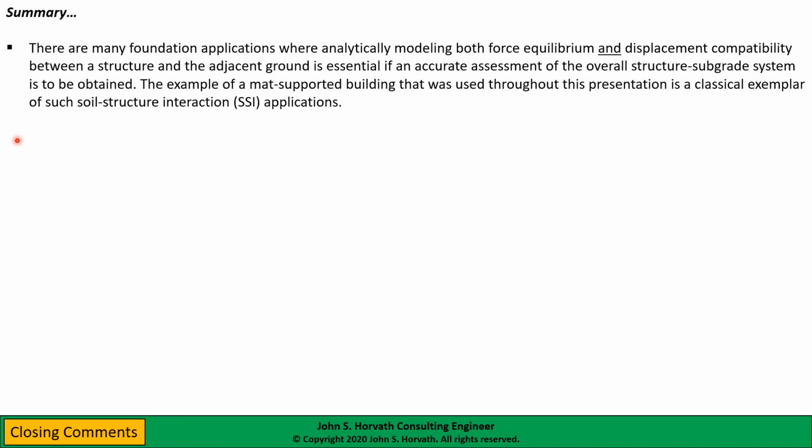There are many foundation applications where we need to consider both the force equilibrium and displacement compatibility between a structure and the ground in contact with the structure. Experience just indicates we need to do this if we expect to get an accurate assessment of how the overall structure-subgrade system behaves. These are what I call soil structure interaction applications, and I've used the very classic example of a mat-supported building throughout this presentation to make these points.